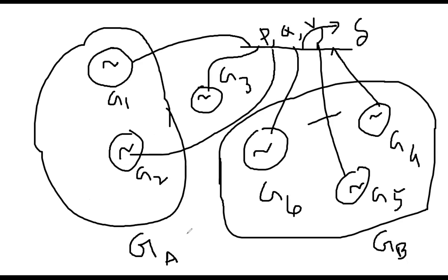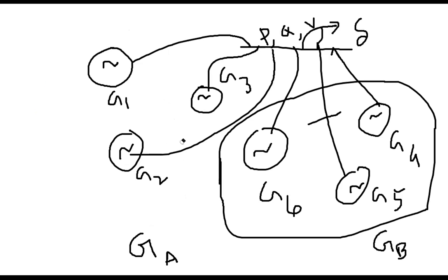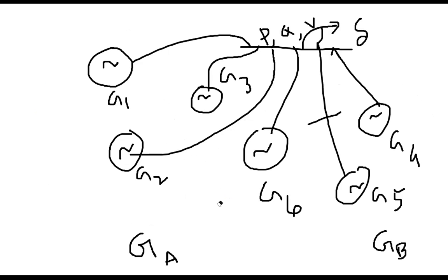So now the question is, what is the criteria? Before making the group, you don't know how to group. First you will plot their rotor angle, in fact the power angle, that delta versus T that we are looking at today. Then you plot it for all generators. For example, for generator 1, just an example, it is going in that fashion.